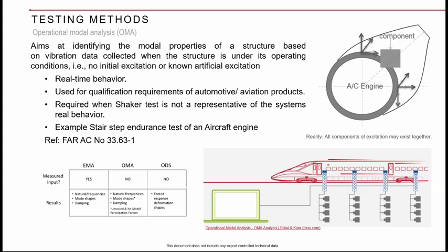That is one thing. So when you measure response from such systems when operated, with various accelerometers on it, whatever mode shape you get can be considered as operational mode shapes. Okay, so that is actually real-time behavior, and in the case of aircraft engines, you will find something called a stage-step endurance test, which can be considered as operational modal testing.